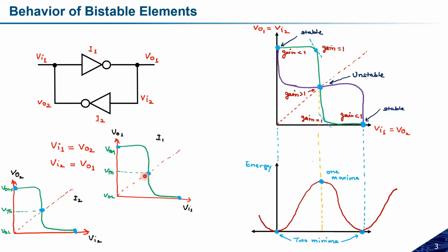Based on all these 4 possible combinations, one of the inverters will come into the logic 0 stable state, and the second inverter will come into the logic 1 stable state, and accordingly they will switch the logic. So this is how we can force this input to a particular state, like logic low or logic 0, which I will explain in more detail when I talk about the SRAM memory. Okay, is the point clear, or is there still some doubt? No, sir, it is clear.